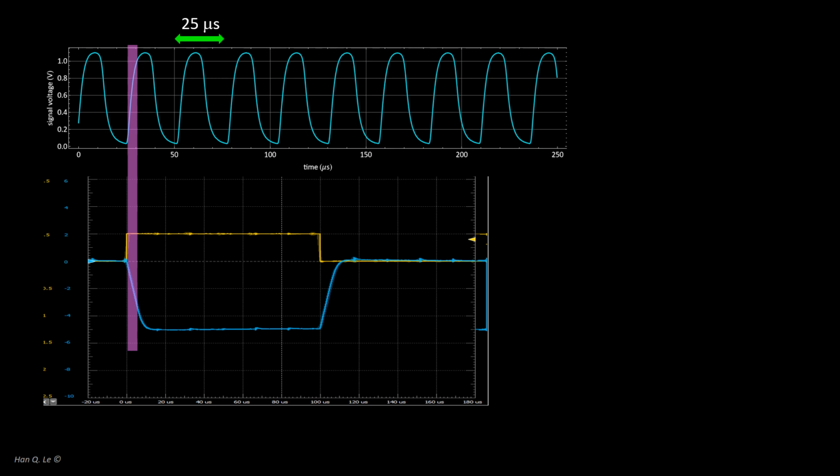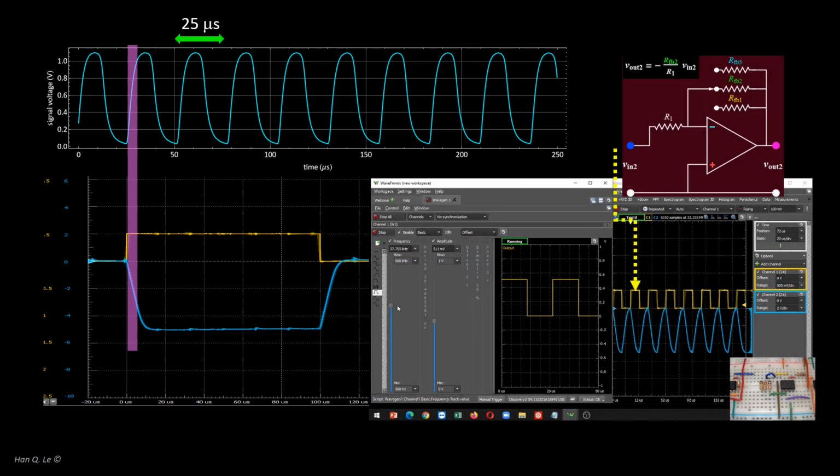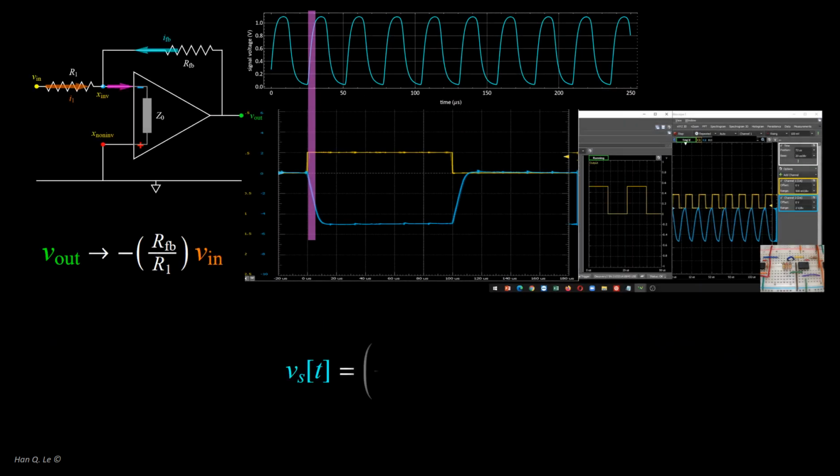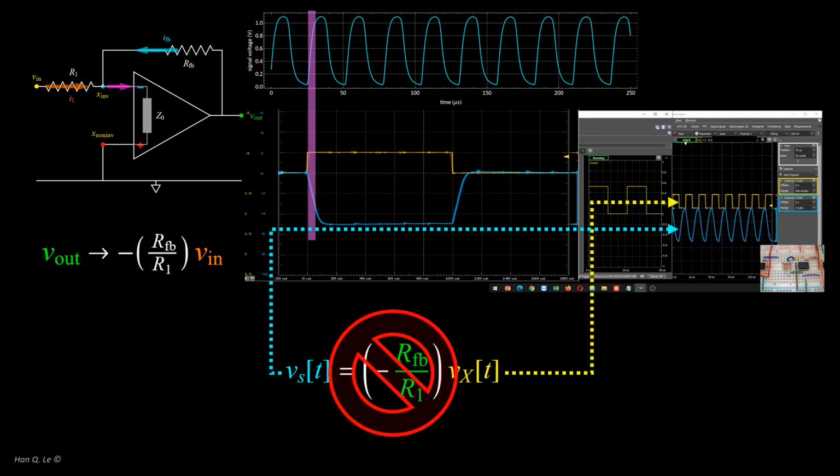Here, it is useful to illustrate the implication of time response or slew rate. In Part A, this graph illustrates the roll-off effect that causes an input square wave to yield a triangular or sinusoidal-like output at roughly 38 kHz. The gain was 14 dB, as evidenced in the lower right corner circuit picture inset, hence the roll-off is slightly worse than that of 10 dB. The bottom line is that these time response and op-amp slew rate measurements of Part A explain the remote control result at the top. Once again, it is worthwhile to remember to never extrapolate a static, steady-state causal relationship to time-dependent quantities.